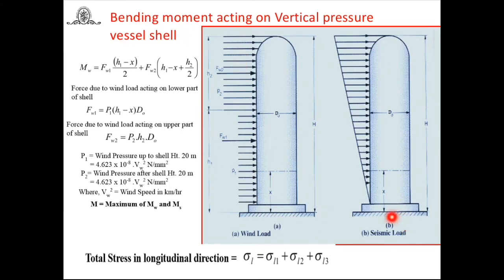Another case here, seismic load. For seismic load, you will find this load is more at the top portion. Again total height is h, its effect is above this x. Consider it's a varying load condition and find out the bending moment.